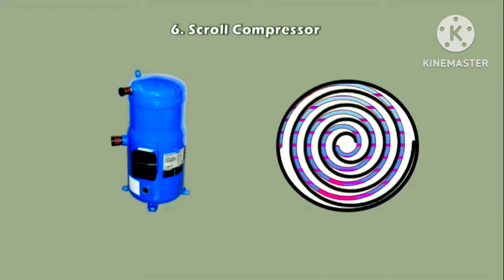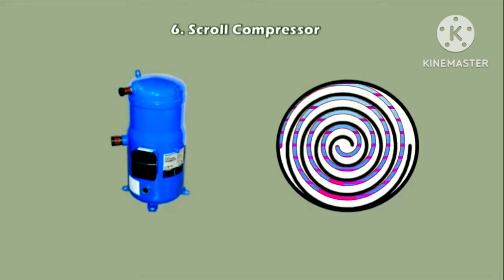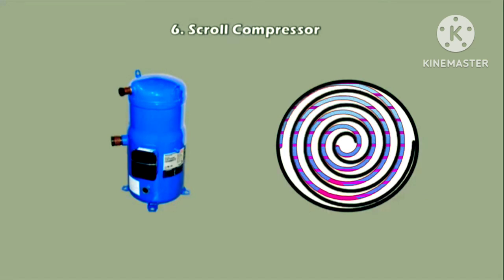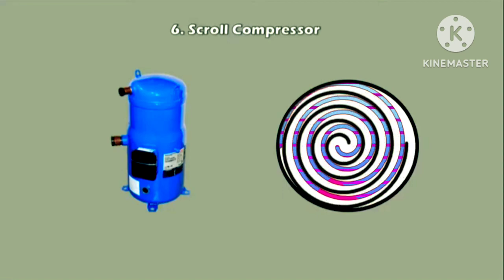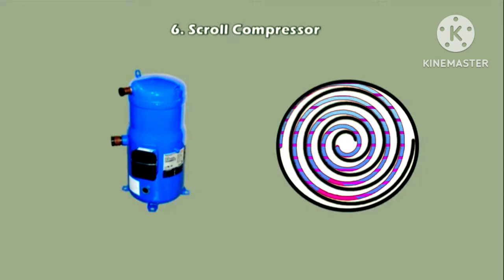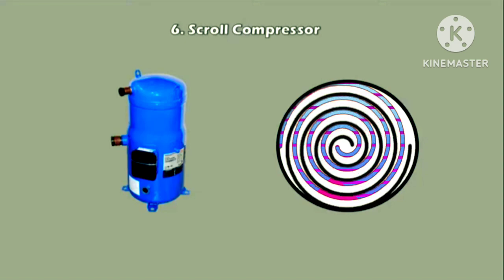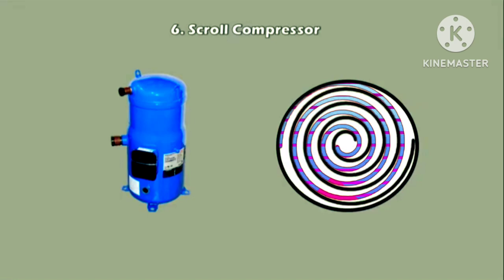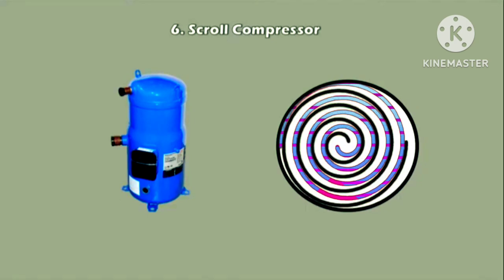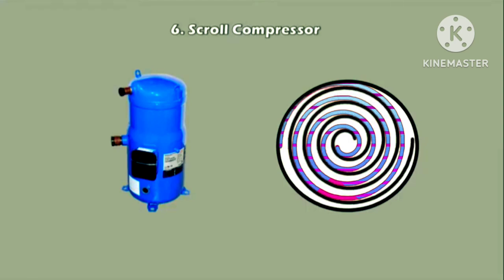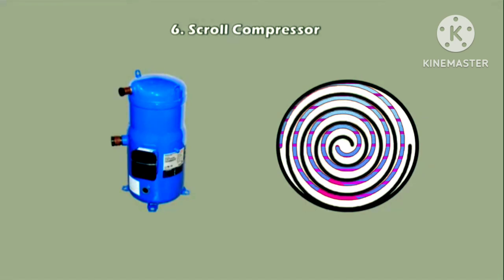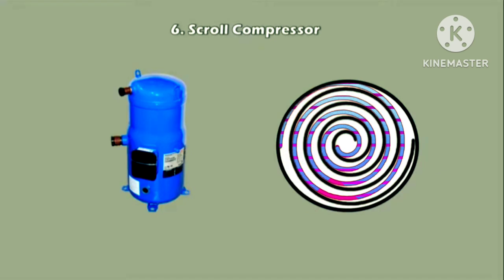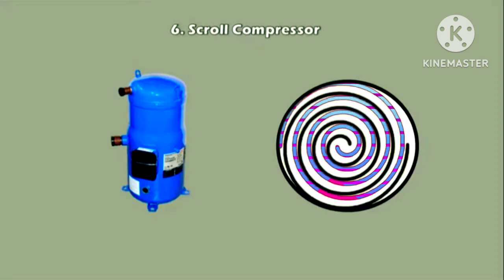Another method for producing the compression motion is co-rotating the scrolls, in synchronous motion, but with offset centers of rotation. The relative motion is the same as if one were orbiting. Leaks from axial gaps are prevented by the use of spiral-shaped tip seals, placed into grooves on the tips of both spirals. These tip seals also help lower the friction and can be replaced when worn down. Some compressors use the pressurized discharge gas to push both scrolls together, eliminating the need for tip seals.